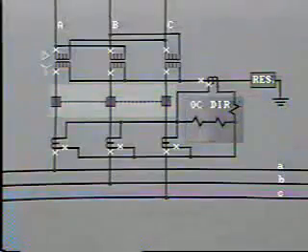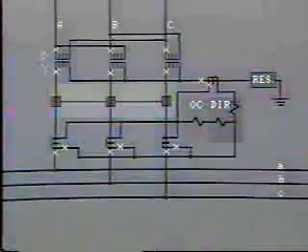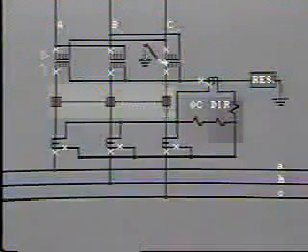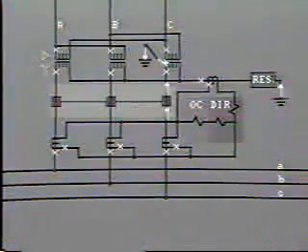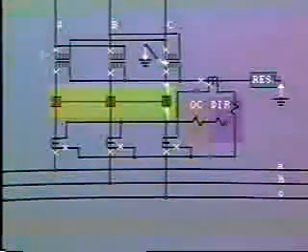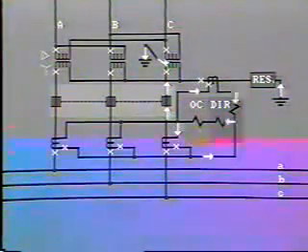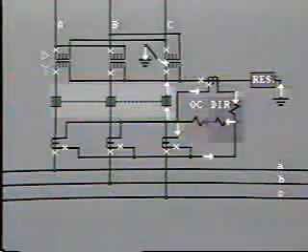Another method of achieving ground fault protection for transformers is by the use of a directional overcurrent relay connected differentially. It consists of two units. The overcurrent unit's operating coil is connected across the line CTs. The directional unit has two coils, and when current flow is correct, it allows the overcurrent unit to operate. Now, for an internal fault, current will flow into the transformer from the feeders through the fault and circulate up the neutral. The circulation of CT secondary current is such that the directional unit picks up. Also, the two currents add in the operating coil and so trip the relay.